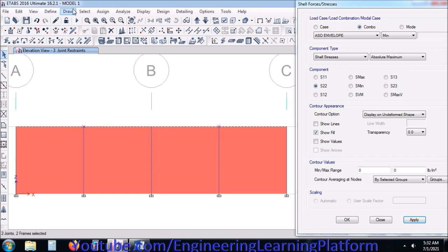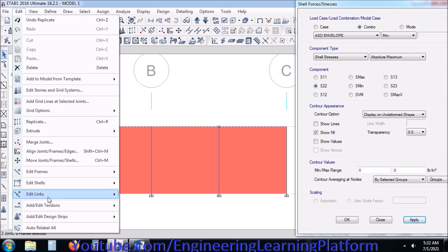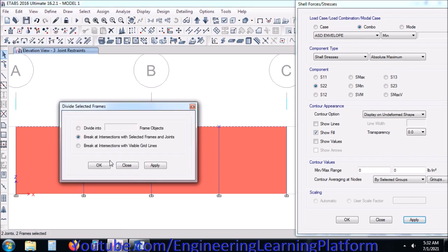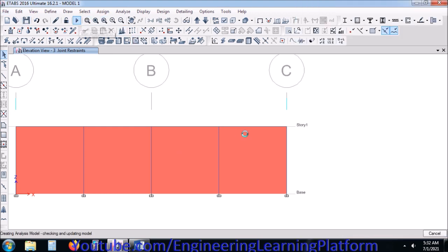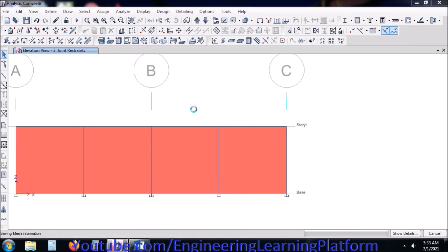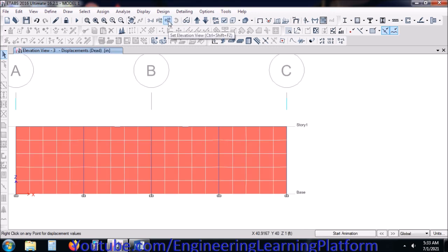And divide the slab here as we add the reinforced edge. The purpose of adding a reinforced edge in the midway of these wall panels is to reduce the stress concentration in the walls, rather transfer them into these reinforced edges. So I'll be seeing if the limit is now met or not.